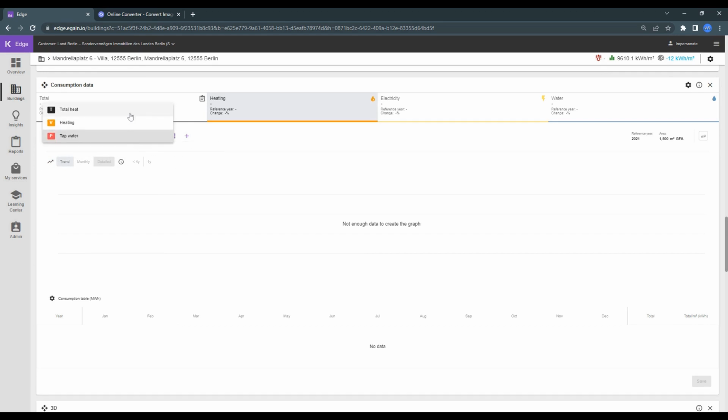And you have a total meter, where the combined stats will be presented, which influences other parts of Edge. Let's start to create the meter logic. The basis is a main meter, which is added manually by us to the system, which includes historical data of heating and baseload, if there's decentralized tap water or a separated tap water measurement. This main meter includes just the heating. To build up the most complex situation, we have in this example centralized tap water and annual stats.